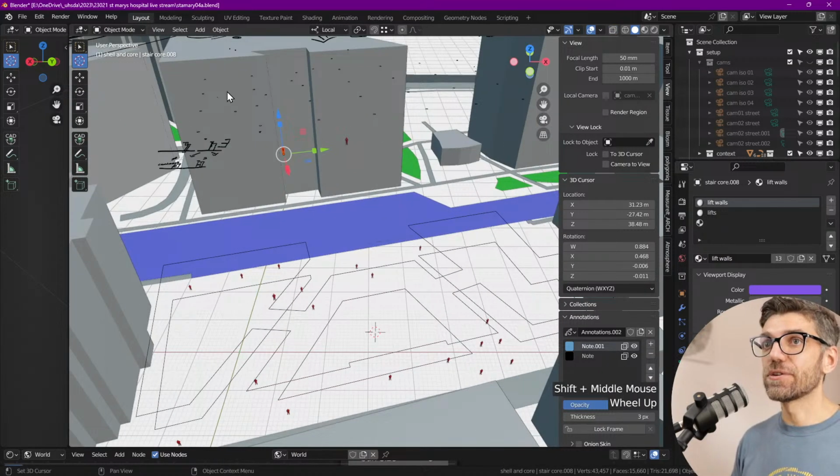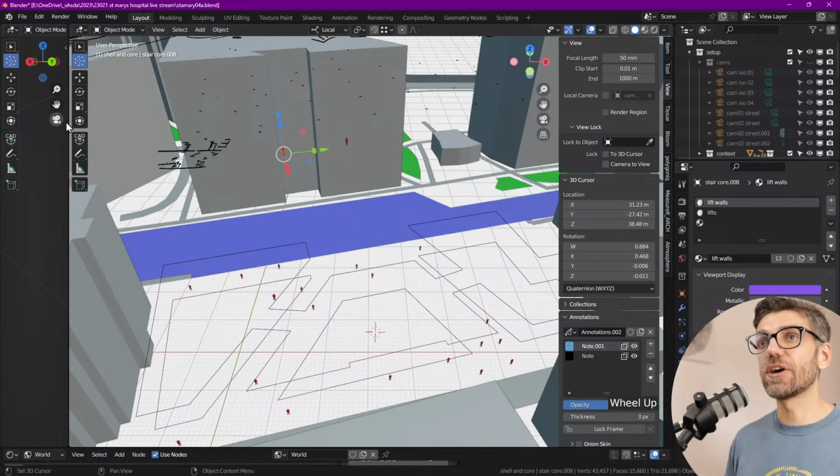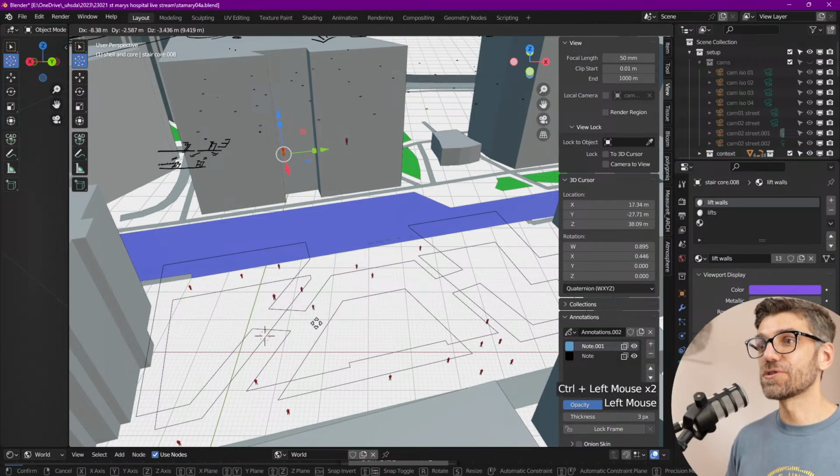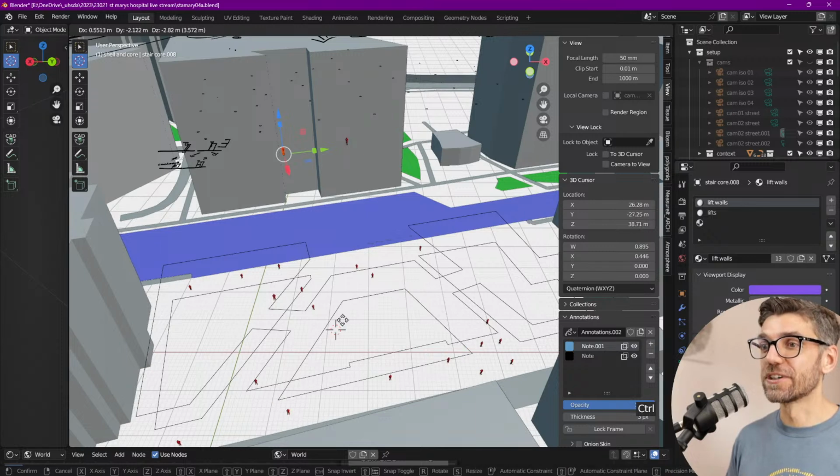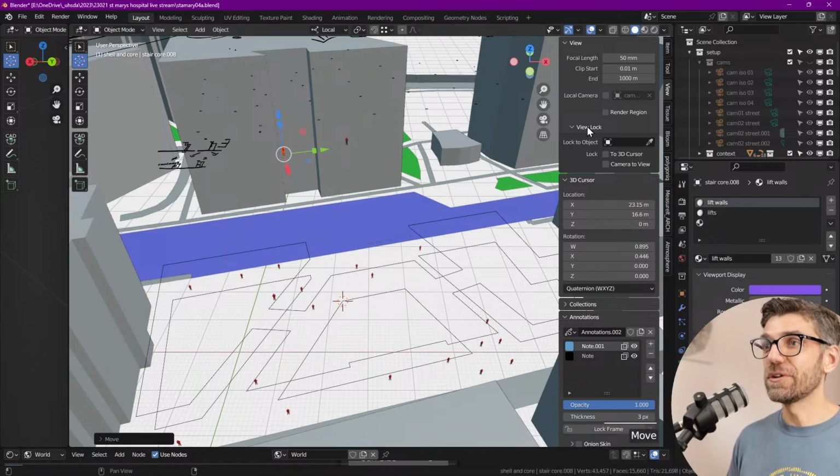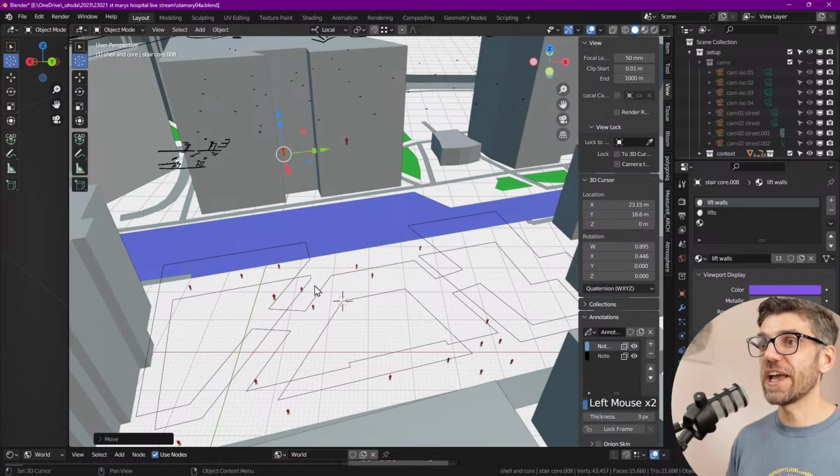That's why. So there's a new feature. This is fairly new. Well, I think it's 3 or 4 versions, but I only recently discovered it. If we hold the cursor, and I click and hold, and I hold control. So first you have to activate it and then hold control. We can actually snap the cursor. So now we know it's exactly on the plane that it should be. Again, that's a fairly new feature, but very handy because it becomes more like a universal snap.